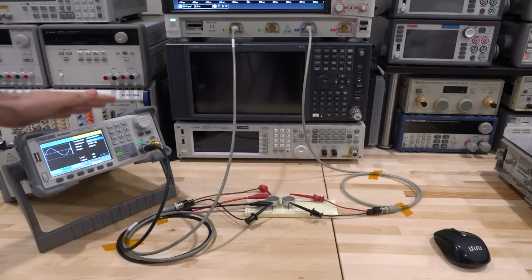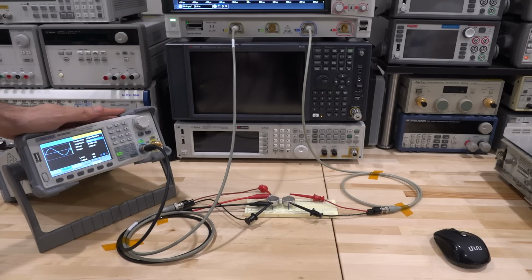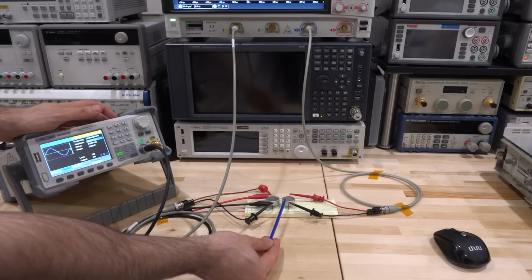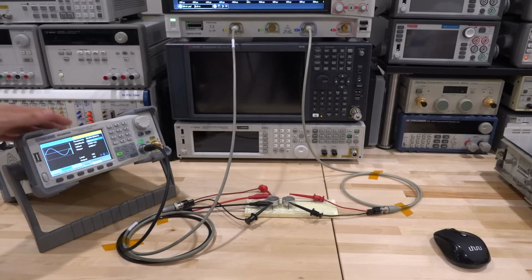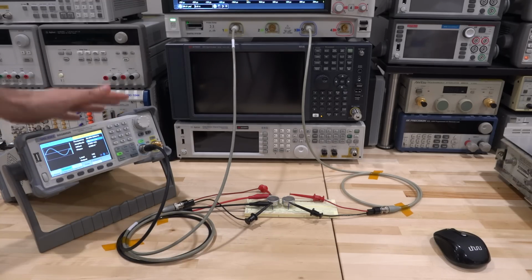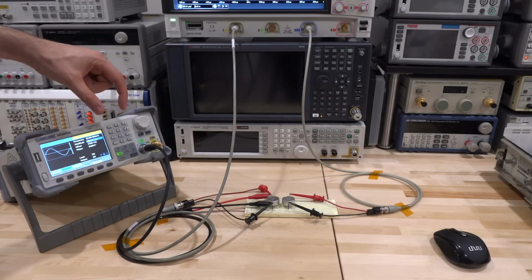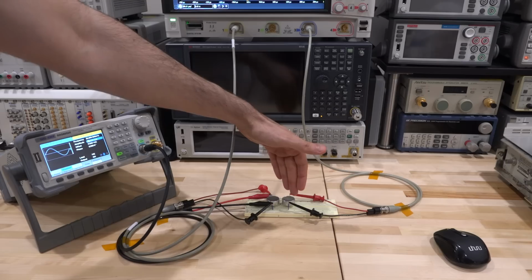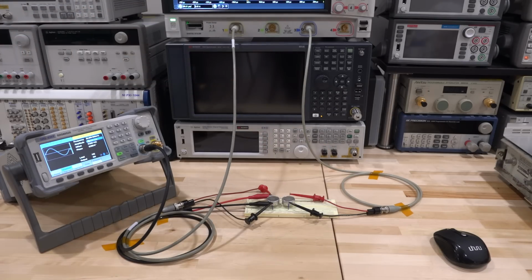Now, obviously, we don't want to apply a CW waveform, because if you apply a CW waveform, when the reflection is coming back over here, you're going to have the signal coupling from the left transducer to the right transducer on top of your reflected signal. So it would be beneficial to create a burst. We apply a burst of signal to the transducer, and then we stop, and then we look at the signal being measured by the second one. And of course, this instrument is easily capable of doing that as well.